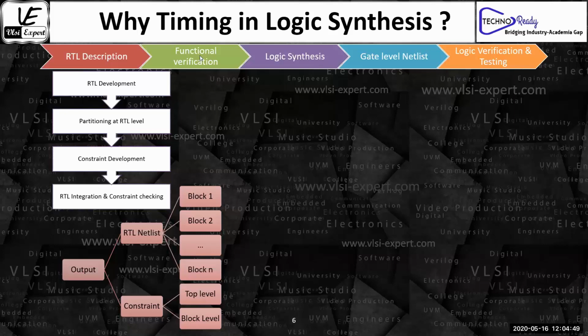So if you have to finish a particular task within 10 nanoseconds, then okay, 4 nanoseconds is going to be part of my outside the block, and 6 nanoseconds I can use inside the block. What this timing related thing is, how the boundary is decided, and how you're going to do that particular budgeting inside the boundary and outside the boundary, we will give you an idea during our session. These are the things we usually do. This is a thumb rule we usually consider in our design.